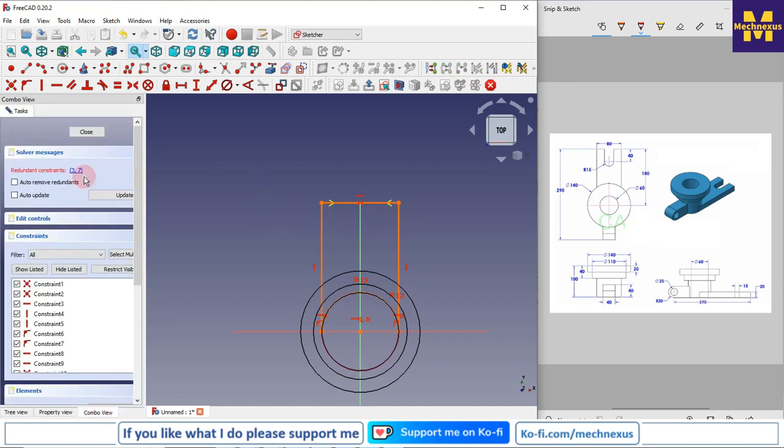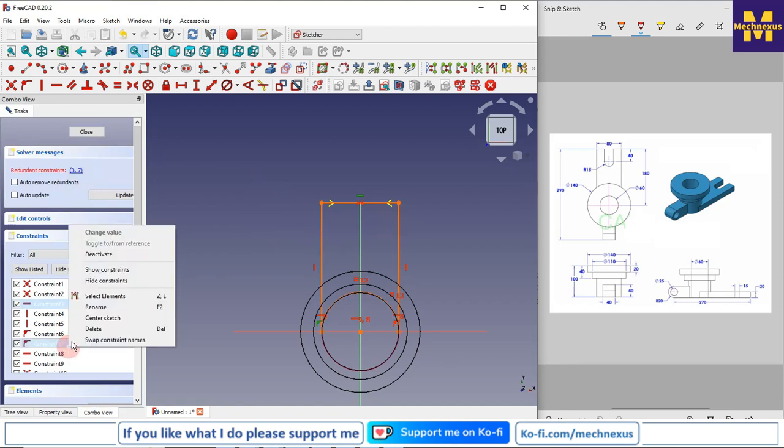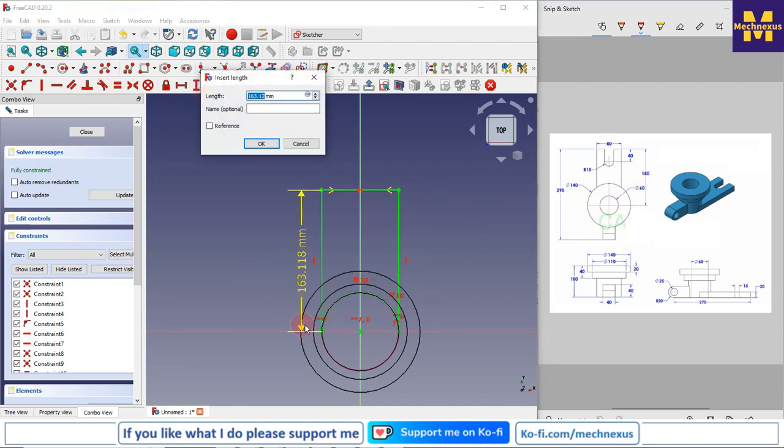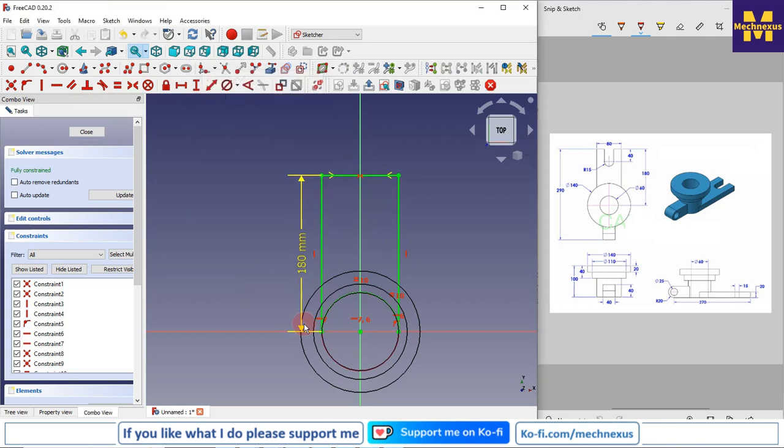I will remove the conflict, so I will delete it. Now we will give the dimension, which is 180. So I will select this line and give dimension 180. So it is fully constrained.